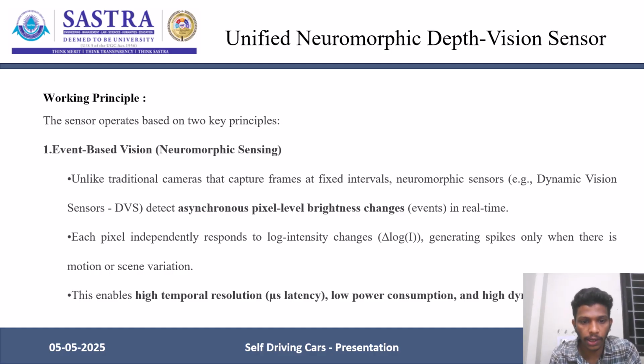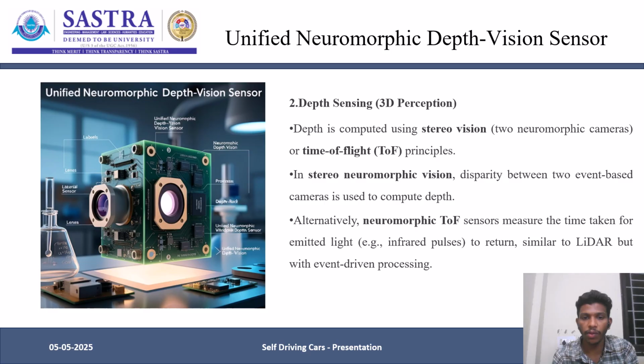Each pixel works independently and responds when it detects a change in light intensity. This eliminates the need for capturing all frames, and enables high temporal resolution, low power consumption, and high dynamic range. When I talk about the second part of the working, that is the depth sensing mechanism.